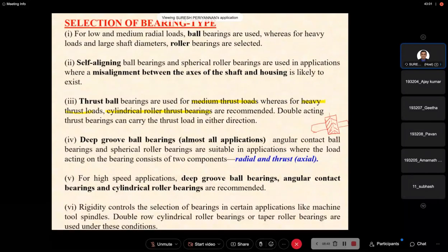The axial thrust is going to be balanced because of this kind of design. Half of the teeth have a helix angle in one direction, and half in the opposite direction. Hence, the axial thrust force will be balanced with this kind of teeth.